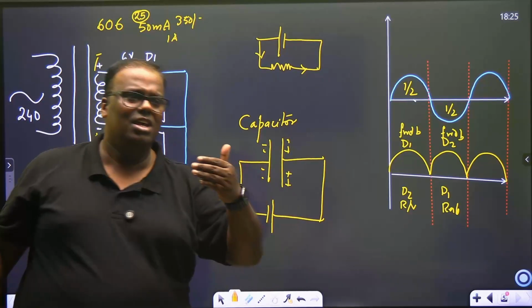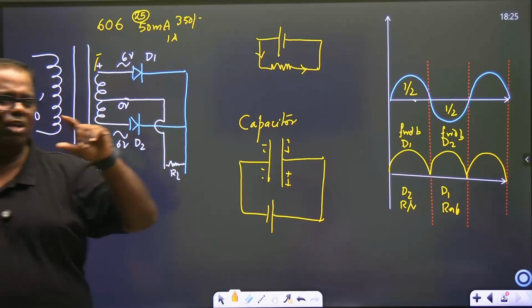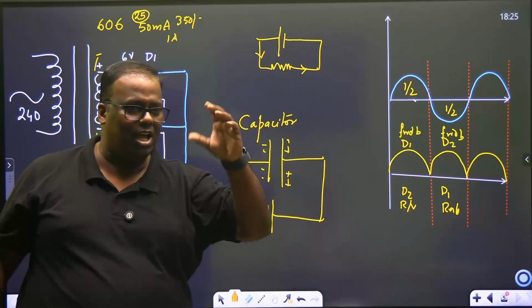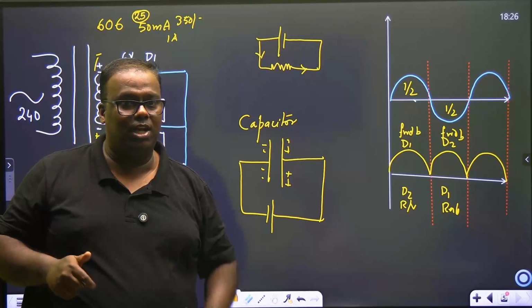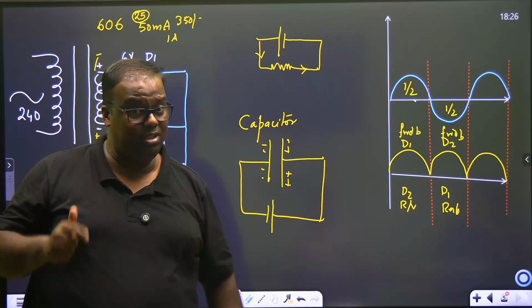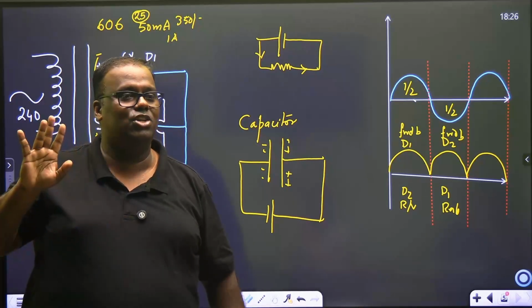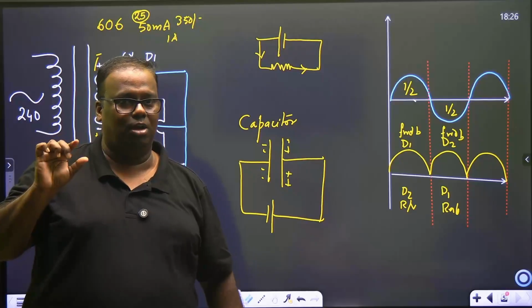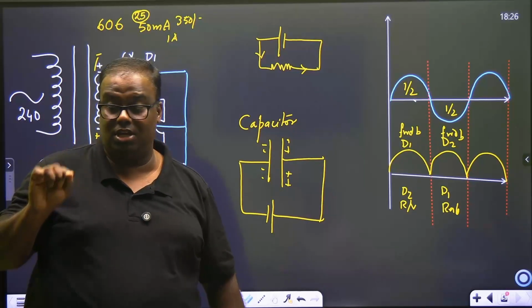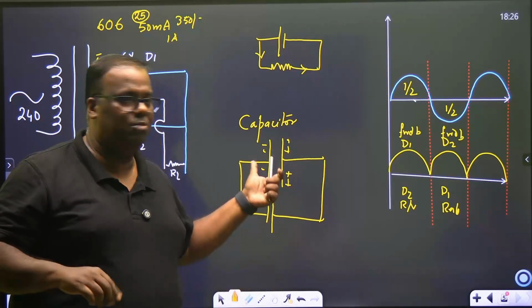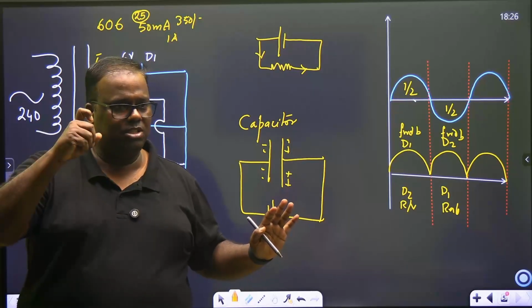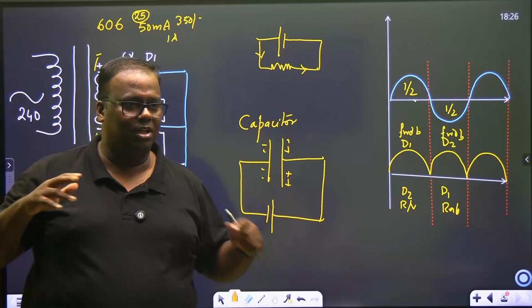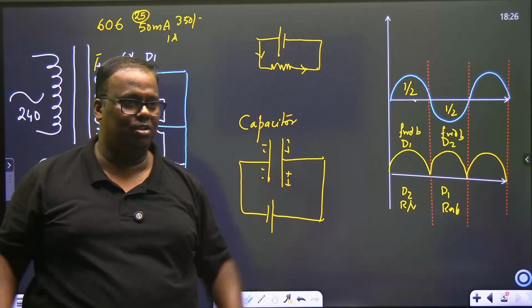If you have a camera which uses an external flash, you will see photographers, when they switch on the flash, it will make a sound. It means the flash is charging up. And then the green light will come up. The photographer will not click the picture until the green indicator comes. Green indicator means the capacitor is now fully charged. Once he presses the shutter, he is not using the battery. It is releasing all the energy in one go.